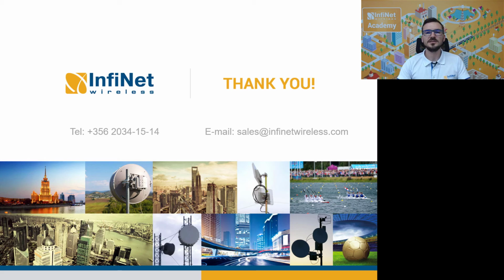And the bad subscriber problem, when you have a very distant subscriber that maybe operates on a low modulation, and it takes a very long time to transmit its data. With polling, all the other subscribers will wait for that bad subscriber to send all its data. But with TDMA, everyone has a fixed time slot, and it transmits whatever it can during that time slot.